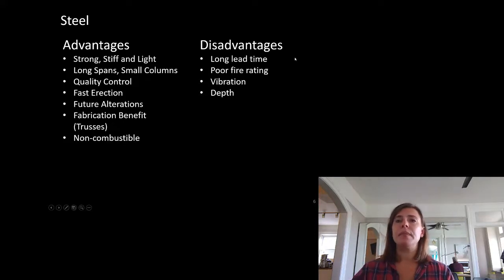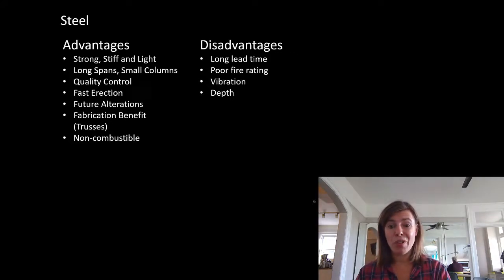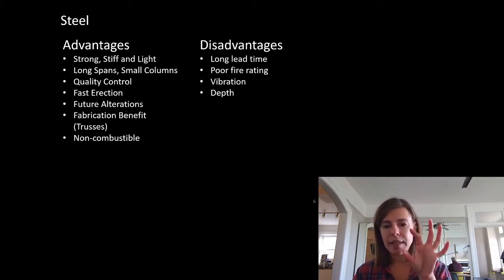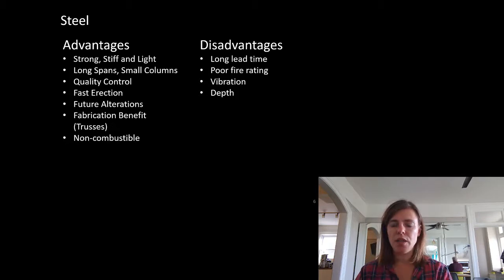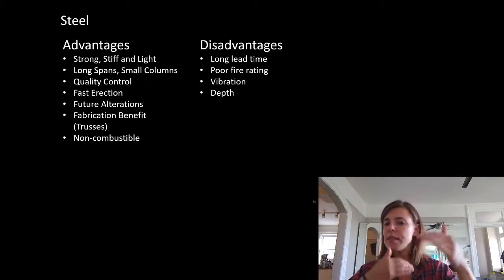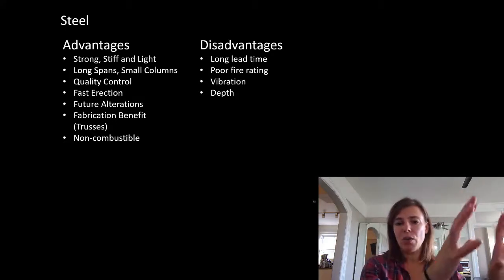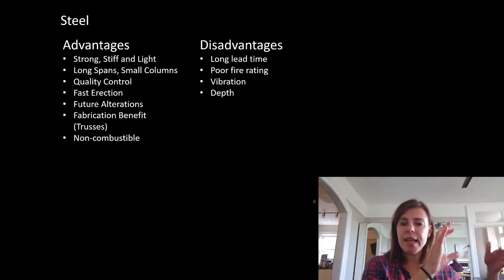Long lead time. It has a long lead time for the exact reasons I said. We have a lot of good quality control issues with it. It goes off to someone who reviews the drawings, creates their own drawings, designs new elements or checks all of the connections, does their own due diligence checks. And then those drawings come back to the base building engineer, who sees if they match their drawings, and it goes back off. They create everything in the shop.